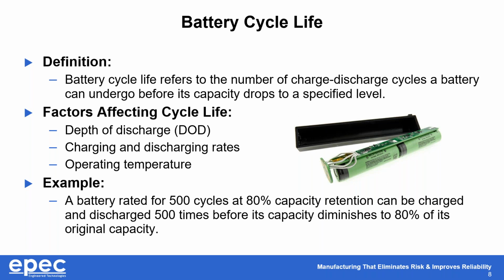Battery cycle life. One of the things that everybody sometimes forgets is that lithium batteries don't have an unlimited number of life cycles. Usually the batteries are rated for 500 cycles before they start to lose their capacity. So basically we can help you extend that by changing how deep we're going to discharge and charge, what the charging and discharge rates are, how we manage the temperature, and how we stop charging or discharging if we get to a certain level. But those are things that we can help you do. But again, that's a very custom design versus something that's a very standard design, which may only have temperature control.